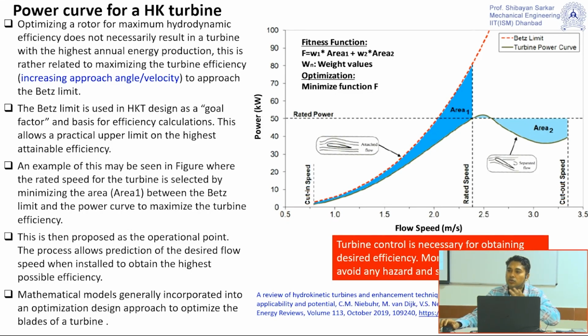So those types of modification: channel modification, turbine blade modification, turbine plate modification, maybe turbine stage modification, that means in different stages you are using different types of blades. So there are different modifications prescribed by different researchers.